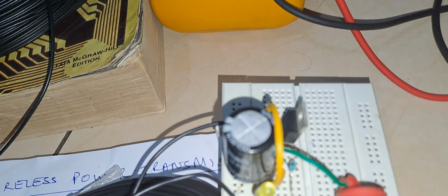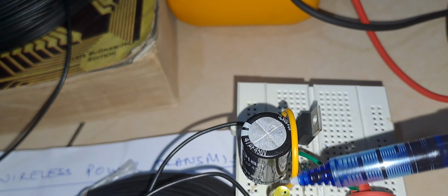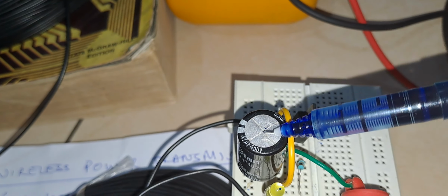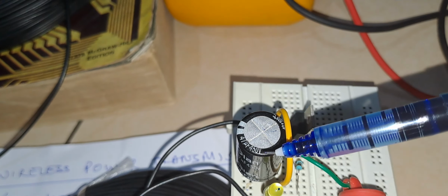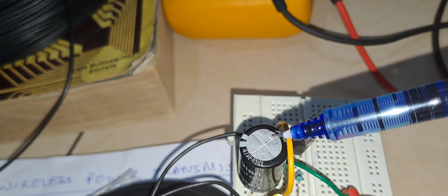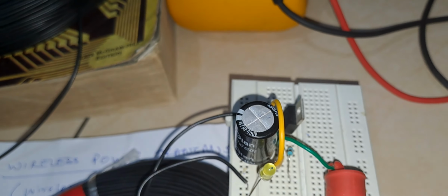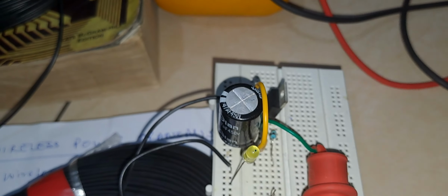And this is the filter capacitor. For now I have used a 47 microfarad 450 volts capacitor. Typically a 1000 microfarad, 63 volts capacitor is better to use. Okay, so now